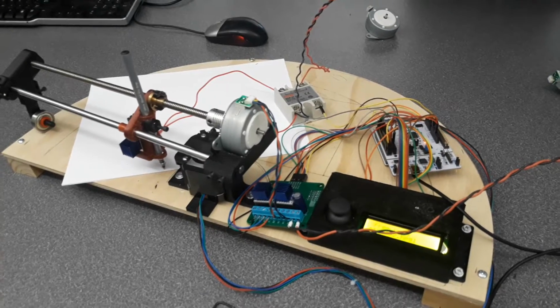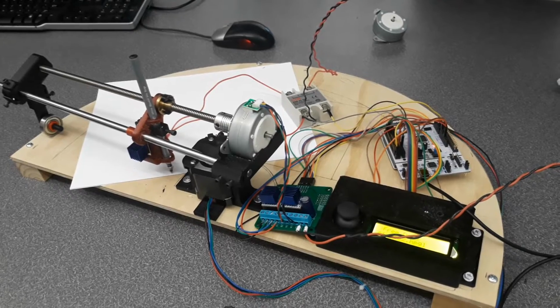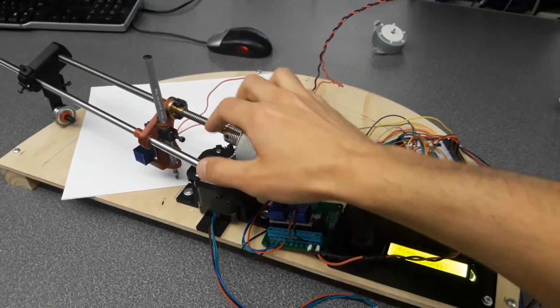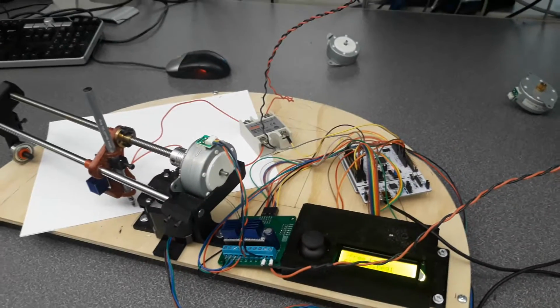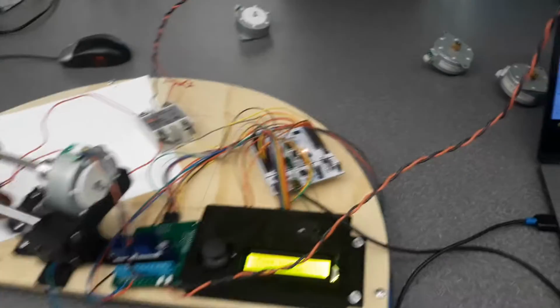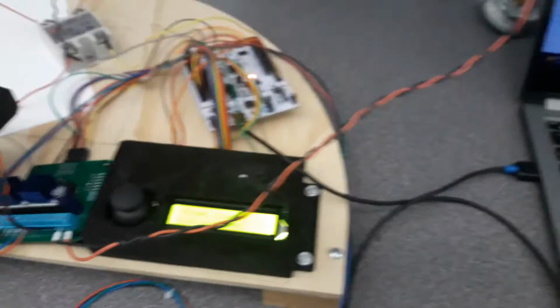This video demonstrates the capabilities of our pen plotter for the ME405 Mechatronics class. The system uses polar coordinates, with a theta motor and a radial motor with a lead screw to advance the pen, and it can draw an image uploaded to the Nucleo board and has a user interface to select multiple files as well as different modes.